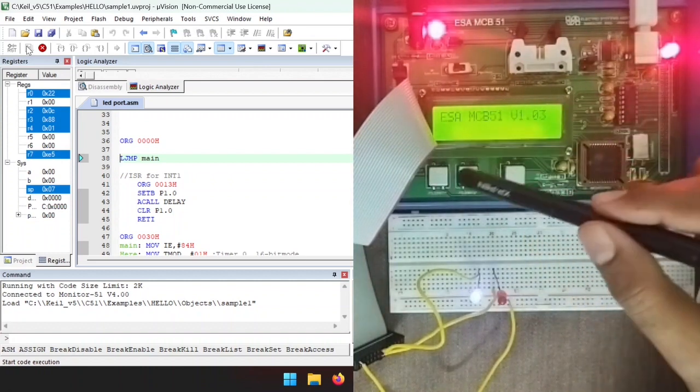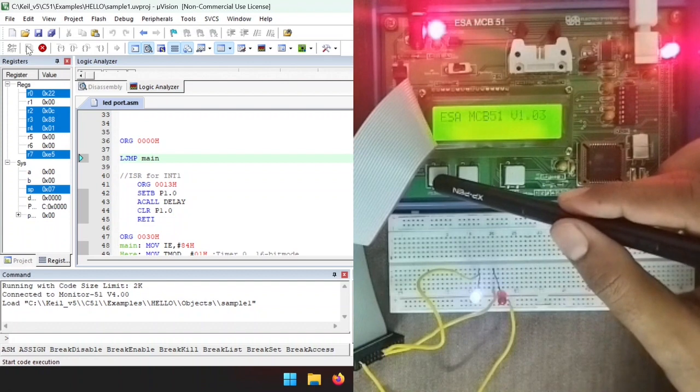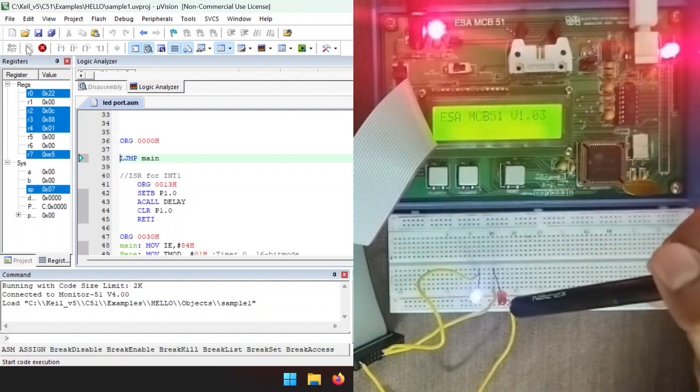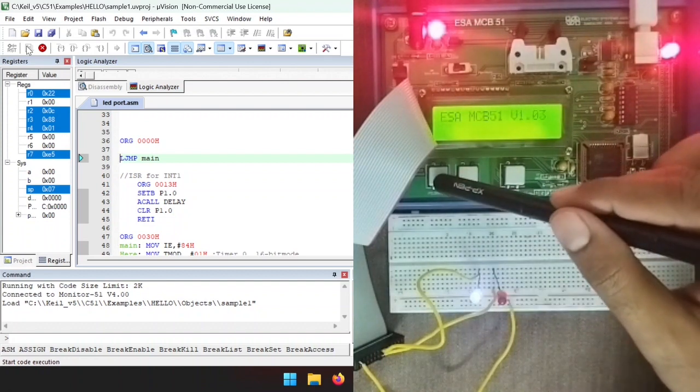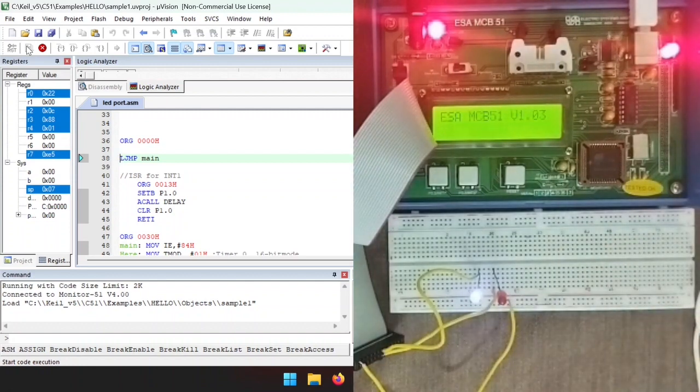Which means if I press this button, your interrupt service routine is enabled. After the interrupt service routine is enabled, I can see my red LED glowing when I press this button. So the ISR routine has to complete its operation and then get back. Like this, it should do its operation again and again if I press my interrupt, right?